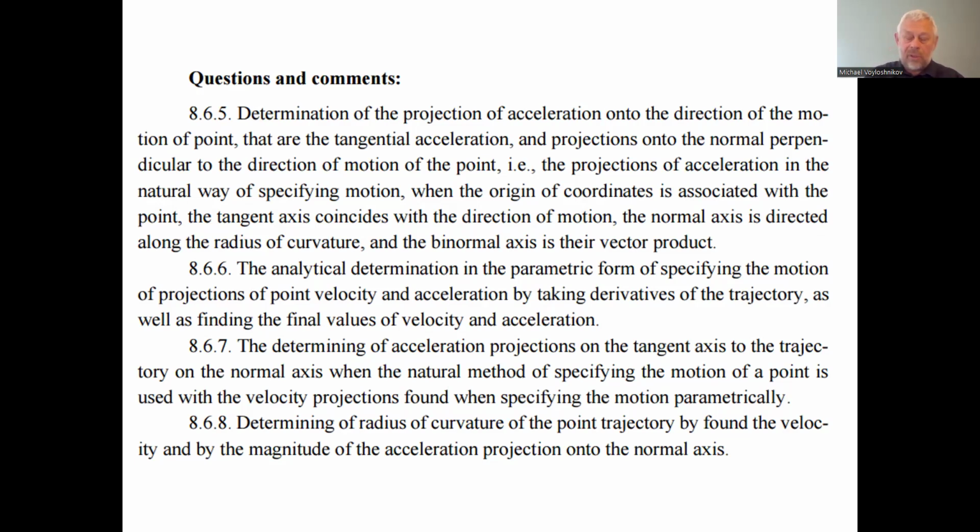In Mathcad, this option is available. In the math operations, we have the option indicated by the right arrow. By the right arrow, instead of equality, if we first predefine the index of the components of the acceleration or the velocity, then in the next step we can find the analytical dependence.